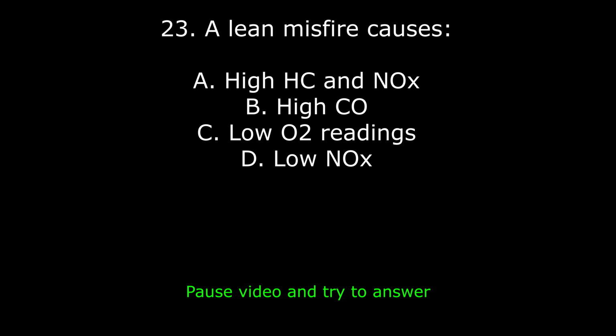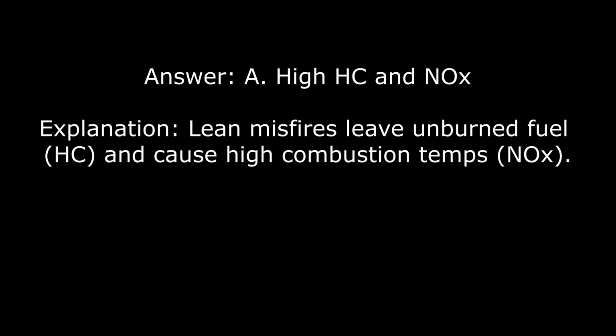23. A lean misfire causes A. High HC and NOx, B. High CO, C. Low O2 readings, D. Low NOx. Answer: A. High HC and NOx. Explanation: lean misfires leave unburned fuel, HC, and cause high combustion temps, NOx.